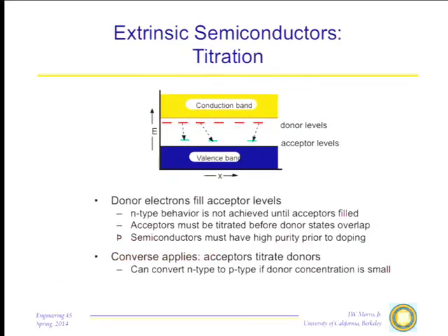There ain't no such thing as a completely pure material. Given the second law, every semiconductor, no matter how carefully you try to purify it, if you're taking a body of reasonable size, it not only has impurities in it, it has a whole periodic table, always. If the material has been purified, that doesn't mean that it doesn't have impurities. It means that the concentration of impurities has been reduced to a very low value, but they're still there. For example, if we want to make an n-type conductor with donors, we have to accept the fact that within that material there are going to be some impurities that act as acceptors and produce impurity levels within the material that lie below the donor level that we're going to use.